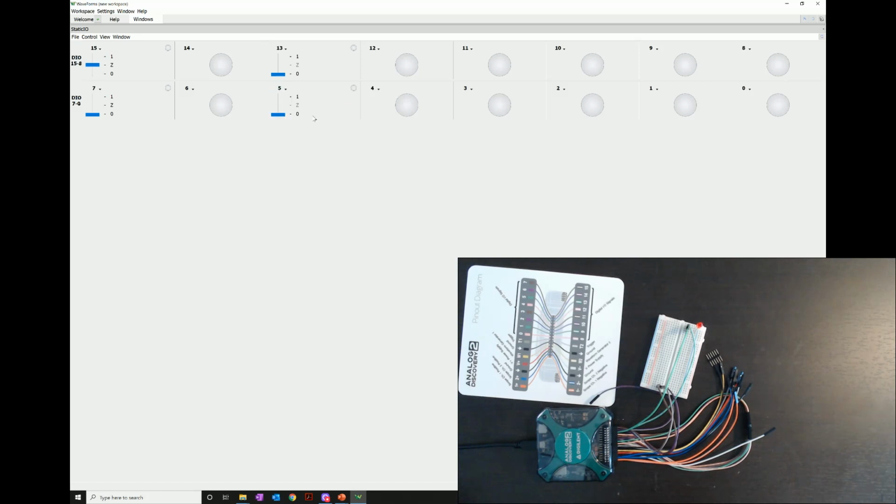And now when we set pin 5 to high and pin 13 to low, we notice that current flows through the LED and it actually turns on. If we set both to low or both to high, the voltage on both sides of our LED is the same, therefore current does not flow through the LED and the LED remains off. Lastly, if we set pin 13 to high and pin 5 to low, then the diode's polarity prevents the LED from turning on and prevents current from flowing in that direction.